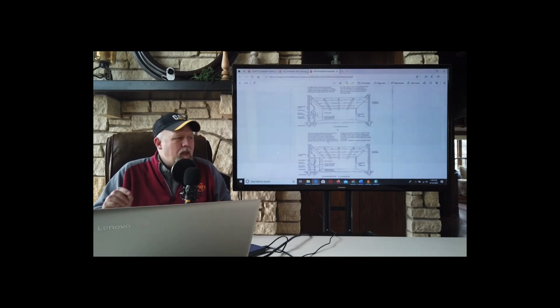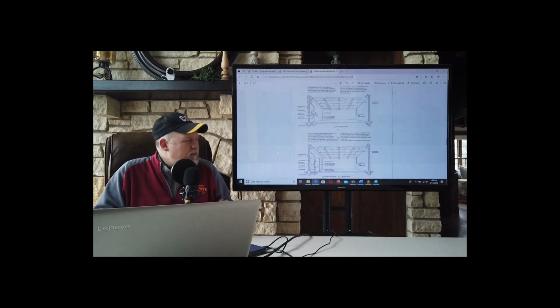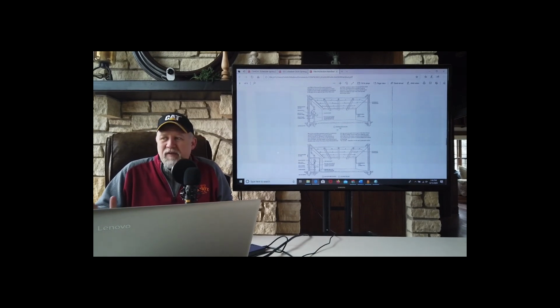In other words, we're most concerned about protecting people's lives, not necessarily all that concerned about protecting property. We have other systems that are better for protecting property, but a lot of times in an office type of scenario, whatever the fire doesn't get, the water will probably destroy. So a wet pipe system is meant to protect people's lives.